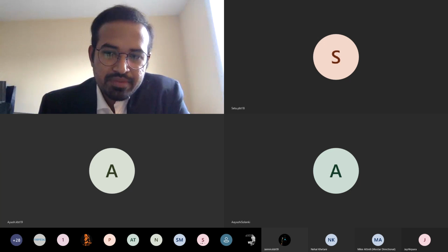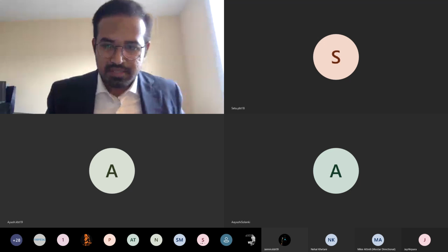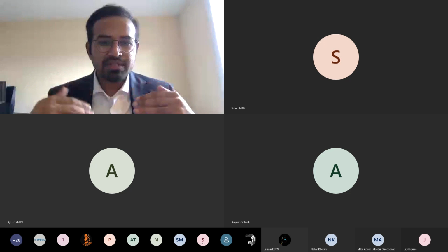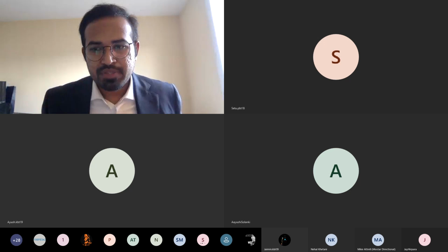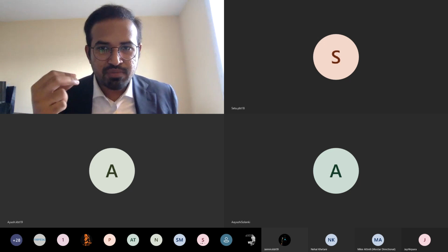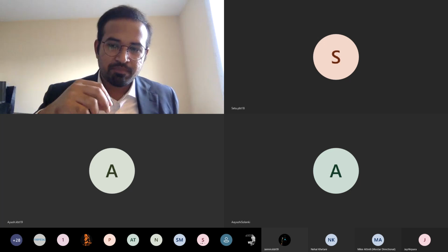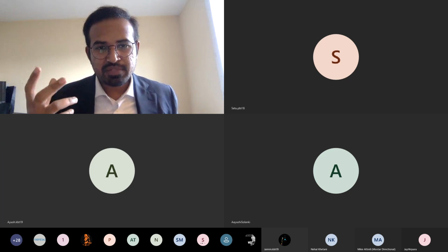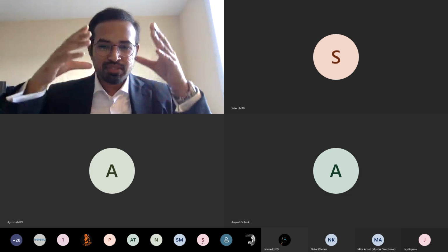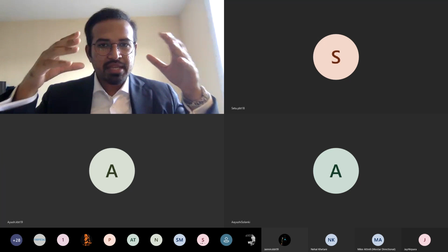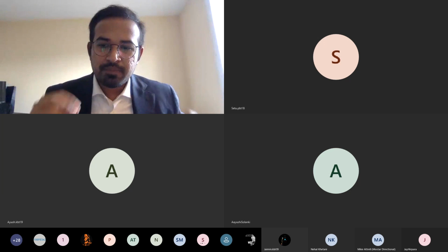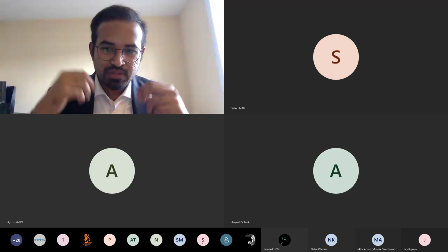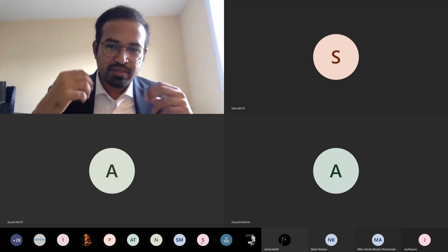Right? So what we have seen so far is, as I just said, when you have a distributed dynamics, there are different dynamics at different time scales. For example, when you have a pressure variation, it just takes a few seconds to a few minutes to travel from the top to the bottom, right? But if we have an influx and a gas bubble that is transported into an annulus, then it will take a few minutes to a few hours for this particular dynamics and the propagation of these waves. So it depends on what type of dynamic that you want to model, or what is your importance for this particular system.